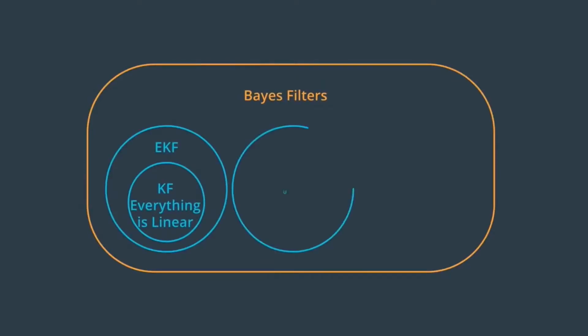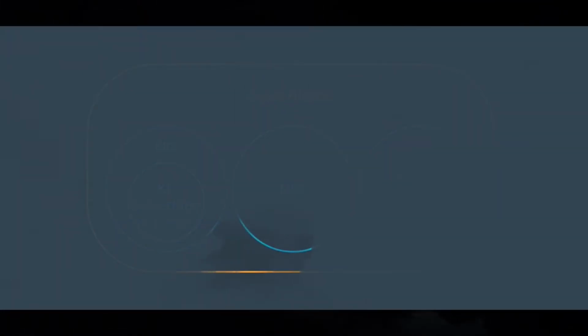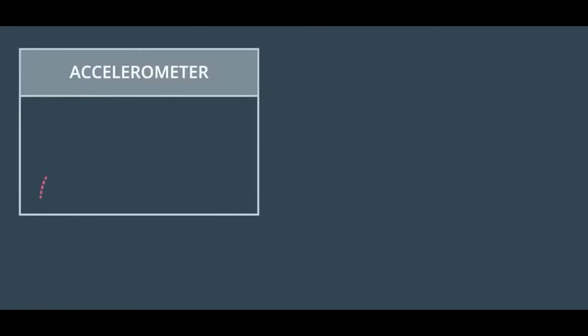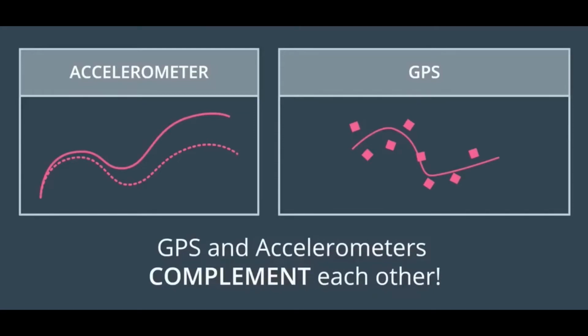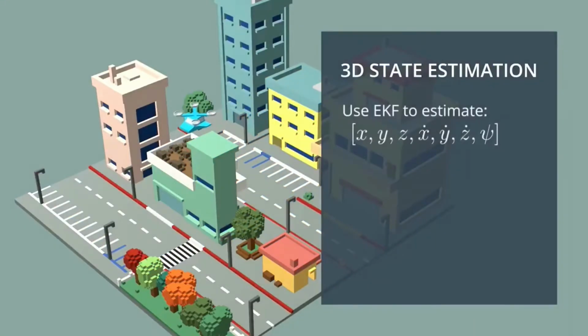The best approach for estimation is through Bayes filters, and the one we used in this project is the extended Kalman filter that deals with nonlinear equations, which we have in our case. The extended Kalman filter, for example, takes the position values that we got through integration of accelerometer measurements that's prone to drift, and the direct position values using GPS modules that are inaccurate, and decides based on previous estimation which sensor should be trusted more, and estimate values closer to it. But as the information we need to know increases, the math gets harder to implement.